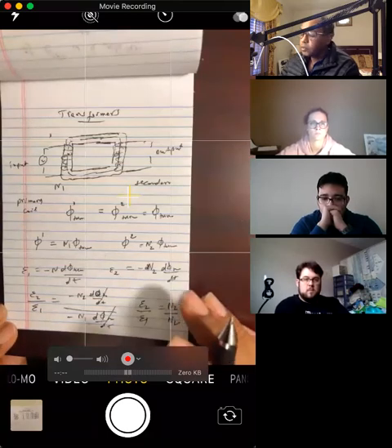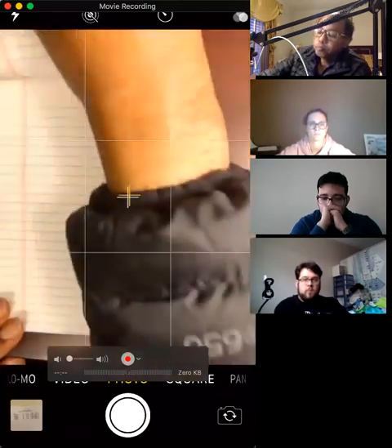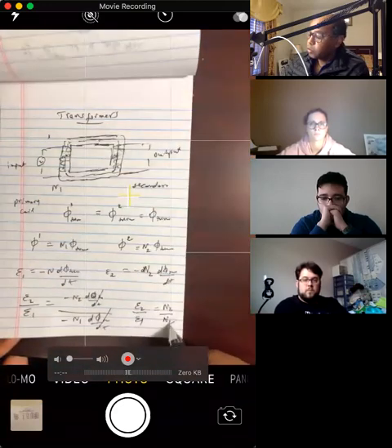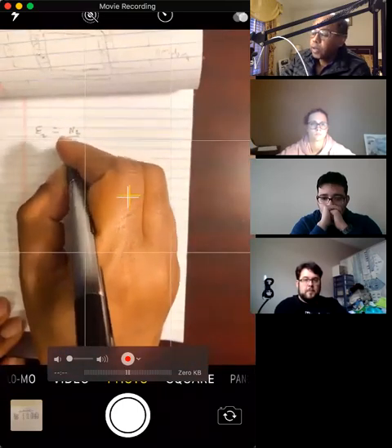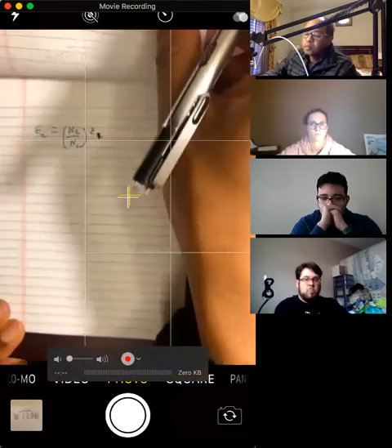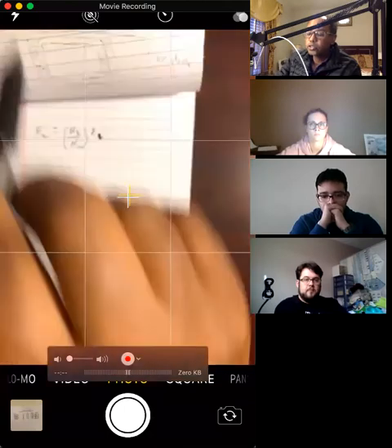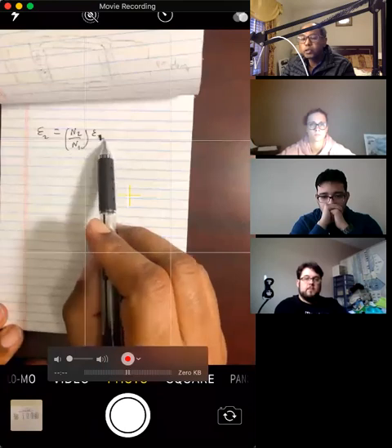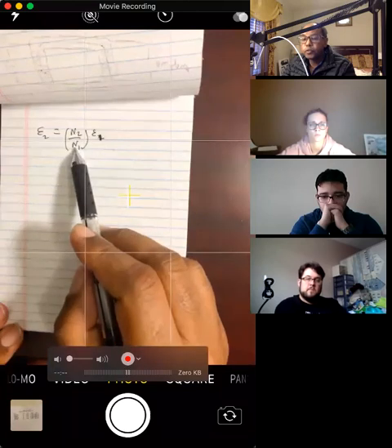You know what that means now? The voltage you get over here, the output, E2, is N2 over N1 times E1. So you can control how much voltage you get out of here by controlling this ratio. Let's say N2 is twice N1, you get twice the voltage. If this is 4 volts and you use 200 turns for N2 and 100 turns for N1, you'll get 8 volts.